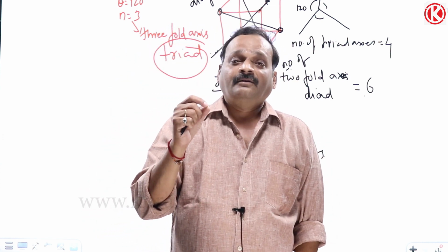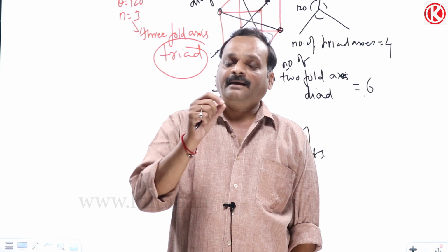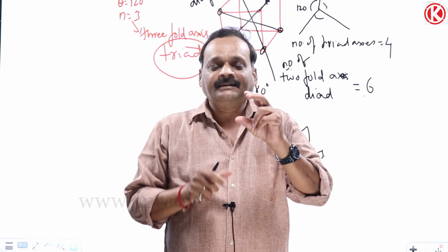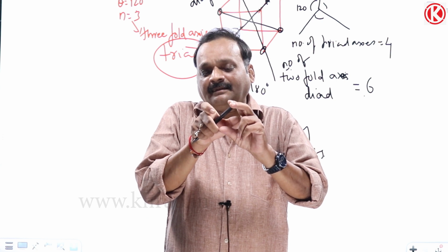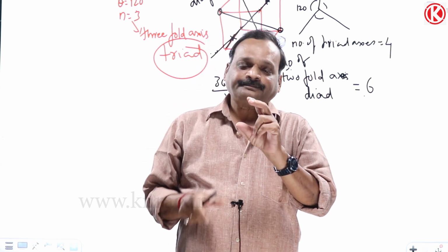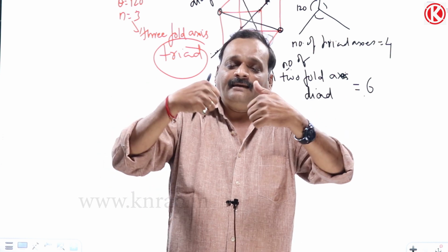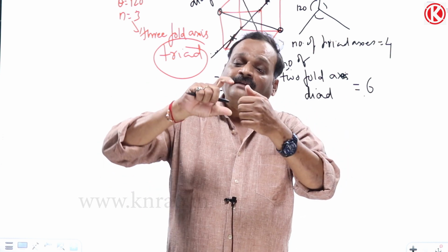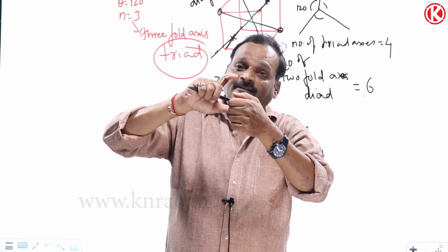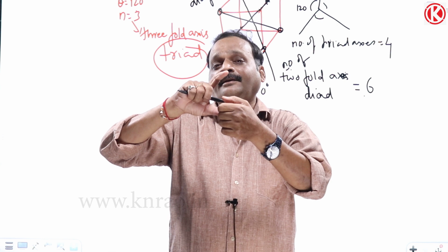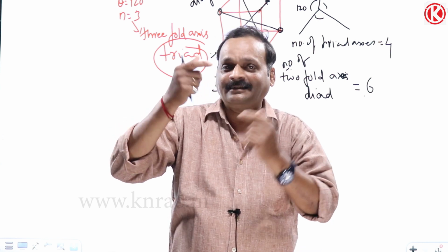Piezo means pressure. Piezoelectric effect means you apply pressure on the crystal in one direction, and in the perpendicular direction an electric potential difference will come. That is known as the piezoelectric effect. Or if you apply an electric field in one direction, along the perpendicular direction there is a mechanical effect, meaning the crystal will either get compressed or expanded. That is known as the inverse piezoelectric effect.